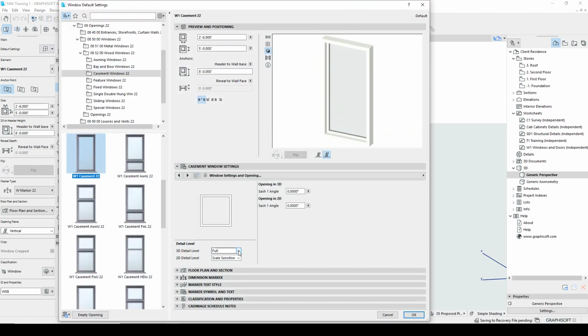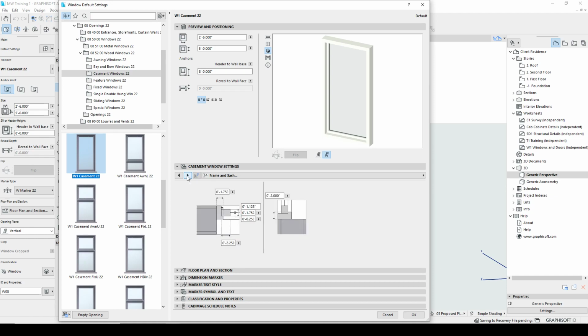And detail. So you have some levels of detail that you want to show. I generally just do full detail. You can set them by the model view options, which is the MVO, and just set it at detailed and full, which will give you the most detailed representation in 2D and 3D respectively. And you can play with that, but unless you're doing a huge project where the windows are just teeny tiny, I generally just keep the full detail exposed in the drawing and in the model.